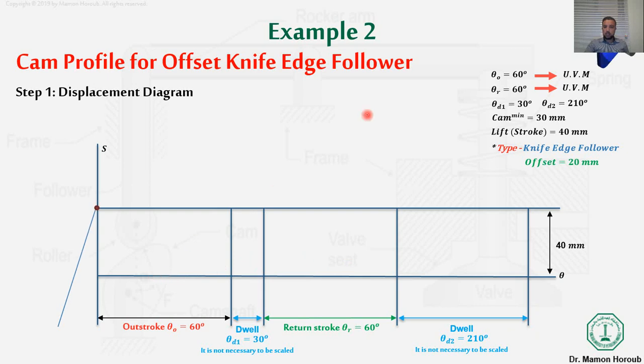If it is 40 here and I need to divide it into 6, as I said, we can use the ruler and calculator, or the acute angle method. We put it at 15 degrees, divided into 6 pieces of 1 centimeter each, and the last point we connect to here. Then drawing parallels crossing those points gives me 6 pieces here.